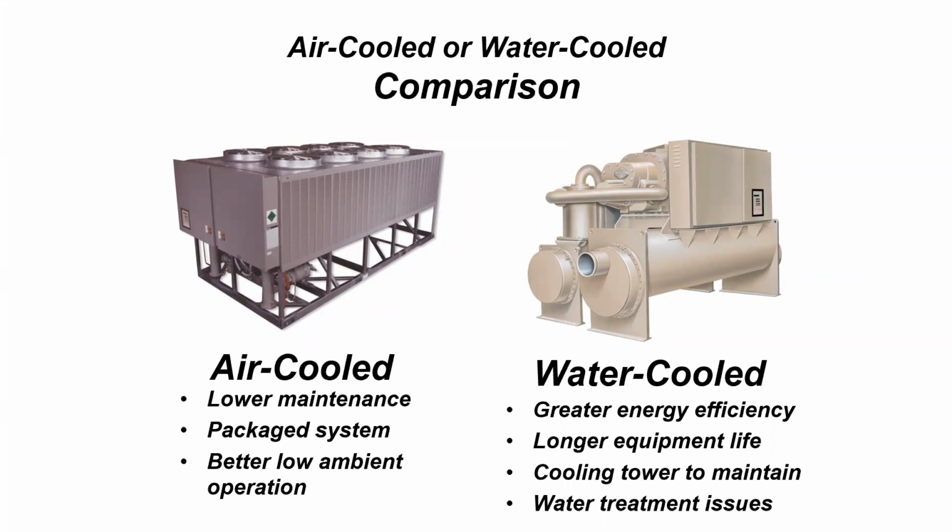On the other hand, if we use a water-cooled chiller, such as in the cooling tower case, the efficiency is much better compared to air-cooled. Longer life for equipment, but it comes with a lot of maintenance costs and issues, such as water treatment, makeup water that should be available, and mechanical maintenance. You have to protect it from freezing in harsh winters. And then you have to clean the chiller condenser frequently as well.